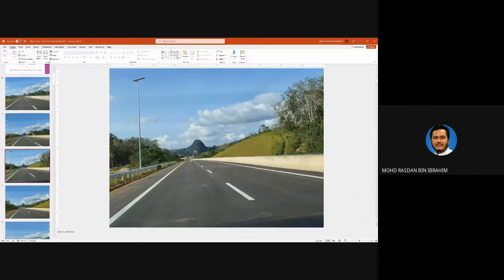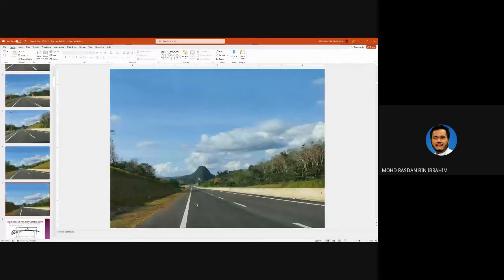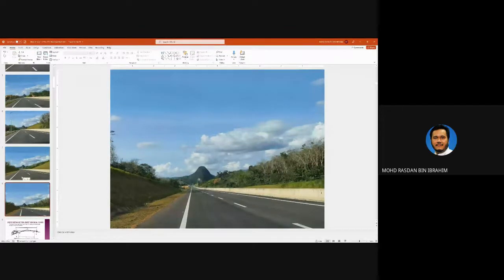Normally, the height of the object that we consider is 15 centimeters. If there is an object lying there, as soon as you can see that object, the distance between you and the object is the S value. That is your sight distance. Okay, all right. So a small part is still hidden. Then here, only can you see the entire pavement of the road.